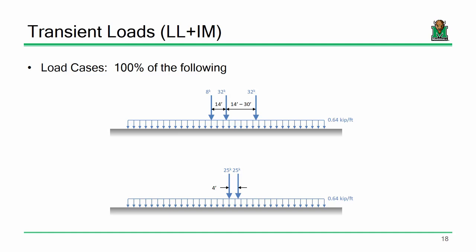So let's just envision a scenario. Here's a bridge. I've got a support here, I've got a support here, okay? Now, let's say here's the truck. I can move that truck up and down the bridge, it's transient. It can be wherever. Let's say I'm trying to generate the maximum possible bending moment that I can. I want this truck to produce as much bending moment as possible. Where would I put the truck? Would I put it over here? Maybe in the middle, right? That's going to make it bend as much as possible, right? And that's what that whole theory of influence lines taught you way back in structural analysis. Don't worry if it's been a while.